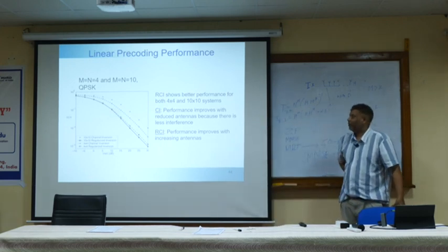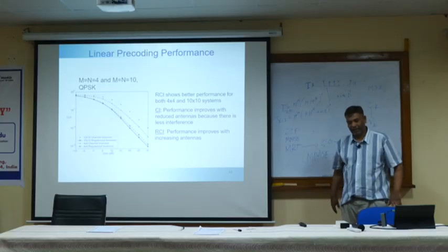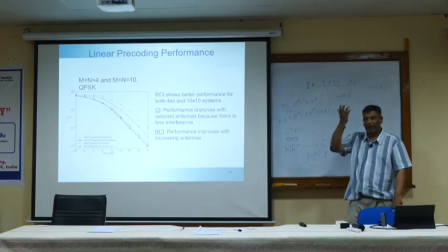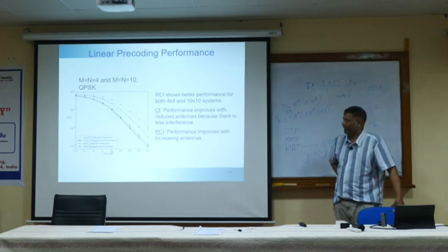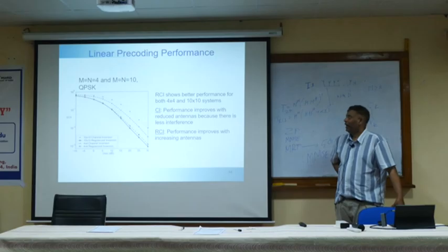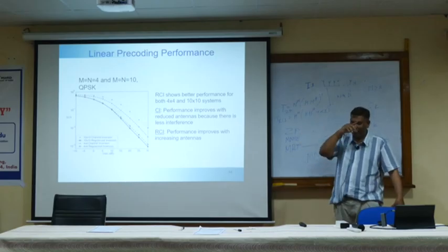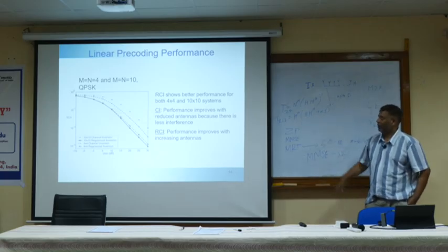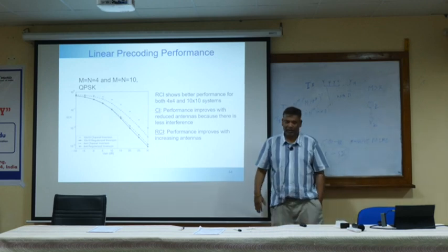Okay, so in 2G and things like that, we used a two-antenna base station. We did receiver beamforming, transmit beamforming, and in 3G space-time block code. Then the MIMO point-to-point system came, specifically for Wi-Fi scenarios. Then that led to multi-user MIMO in 4G, and then 5G became massive MIMO.